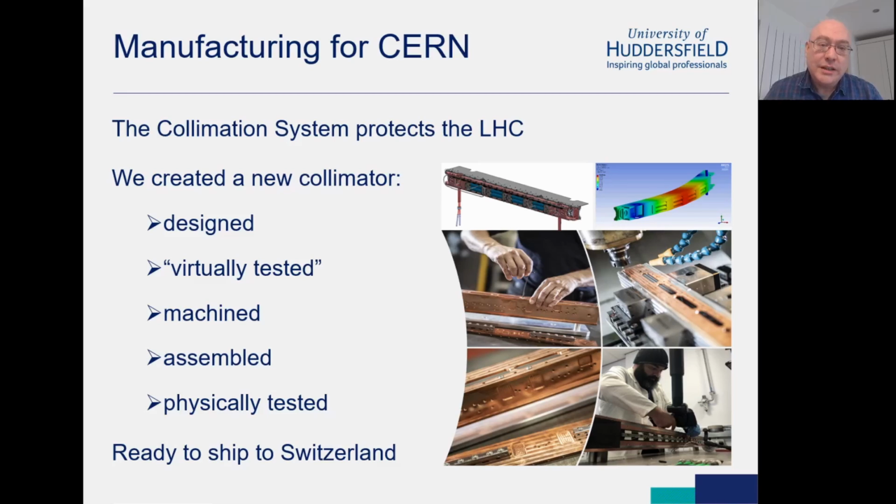So here is a design of the new collimator using some quite exotic materials that were required to fit into that high radiation environment. Actuators, which are the bit that allows us to make adjustments, and sensors that mean that we can detect there's been something bending and we can push things back into alignment automatically. We've then got to think about the control loop.